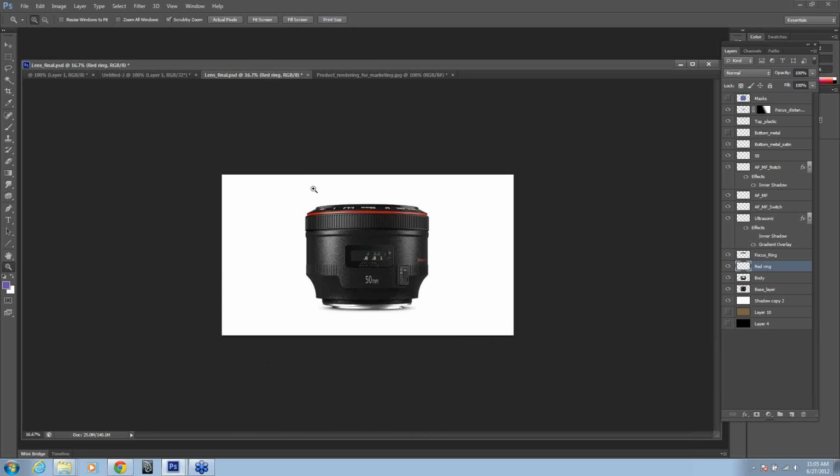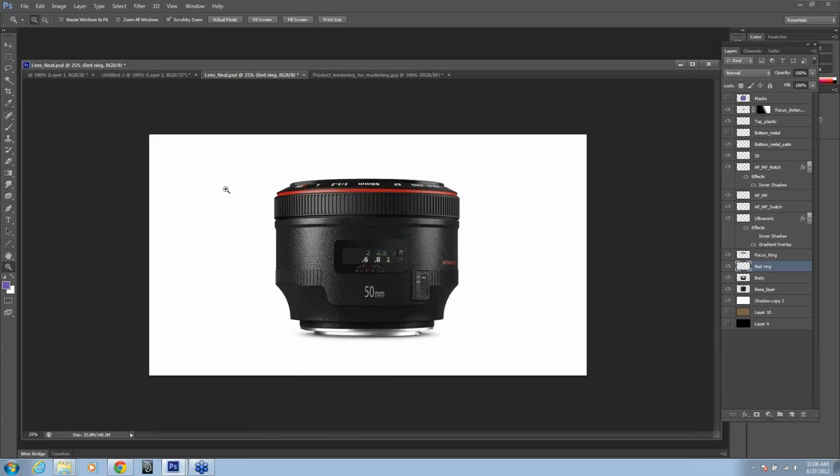One of the things that you'll notice about KeyShot is it's great for doing high-resolution images, and it's great for being able to import high-detail models. You don't really have to be concerned with the size of your 3D model when using KeyShot, because KeyShot does not rely on the graphics card. Everything that KeyShot does in terms of rendering is done on the CPU. So that means it can run on just about any machine, and you can get really high performance. This image and most of the images that I do are all created from my laptop.